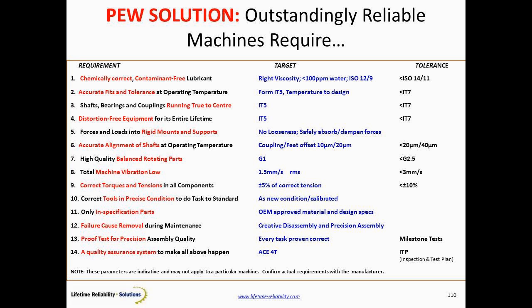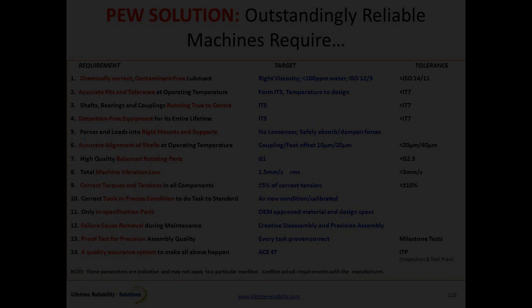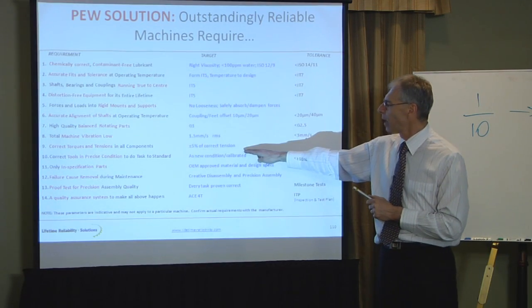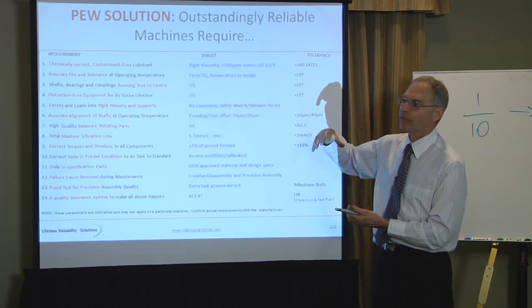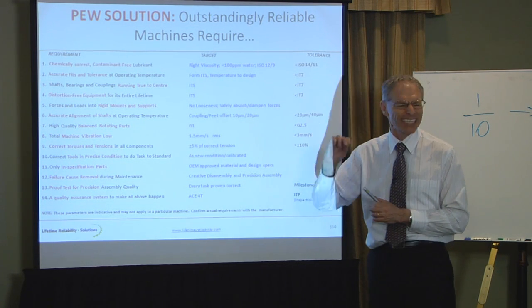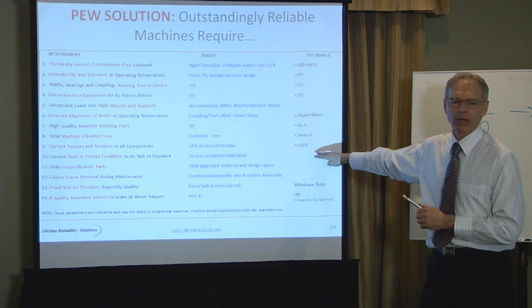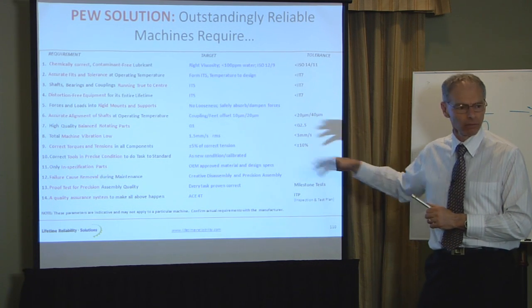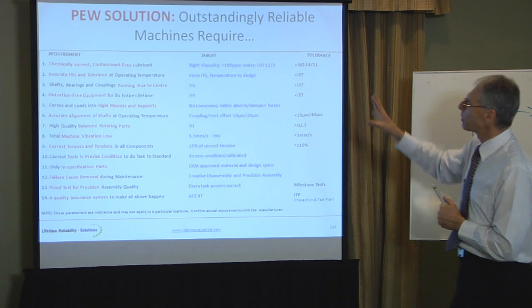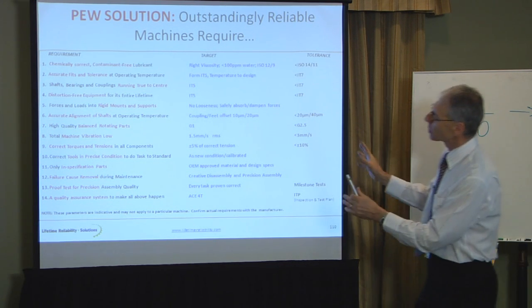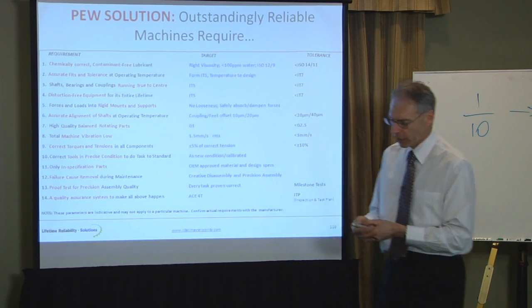Now each machine, each manufacturer, they might change. So this is representative of what we're trying to achieve. Those actual numbers depends upon the particular design of the equipment. So these aren't universal, they're indicative of what we're trying to drive towards. Tension accuracy in our fasteners of plus minus 5% would be fantastic. But I will accept up to plus minus 10% before I begin getting worried about our practices. So this particular table is giving us some parameters to work to these 14 aims.